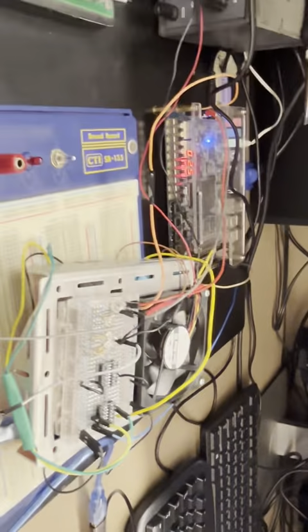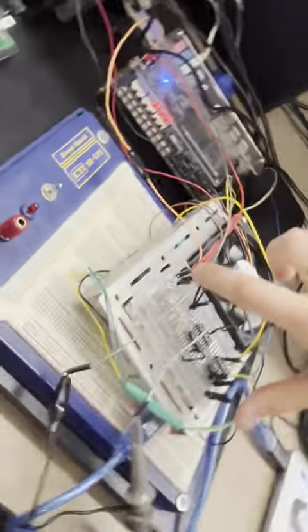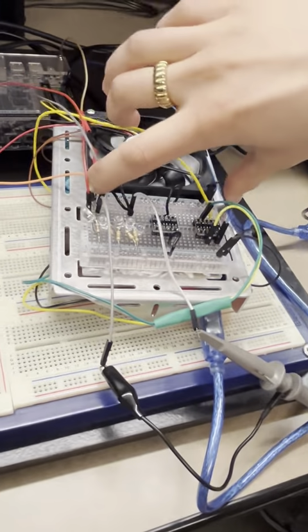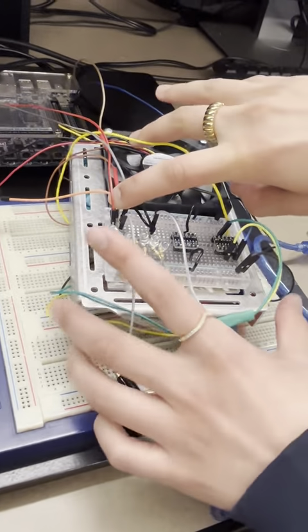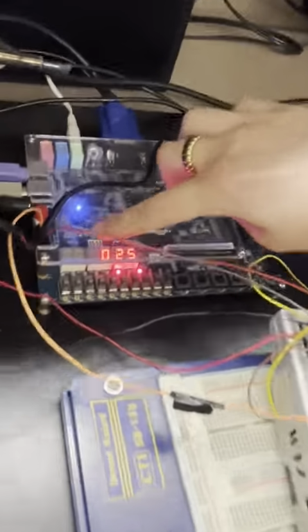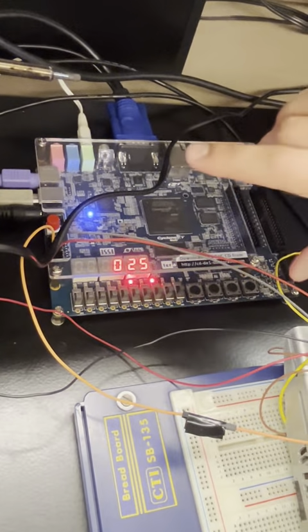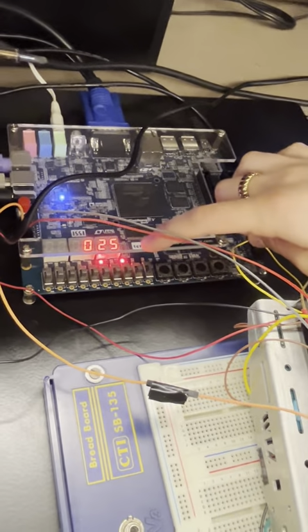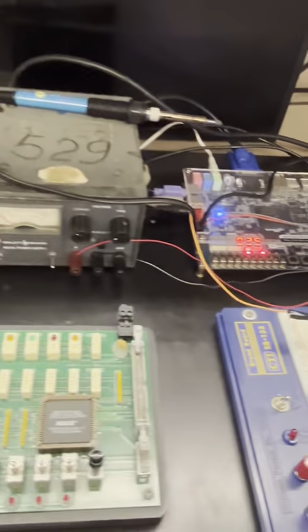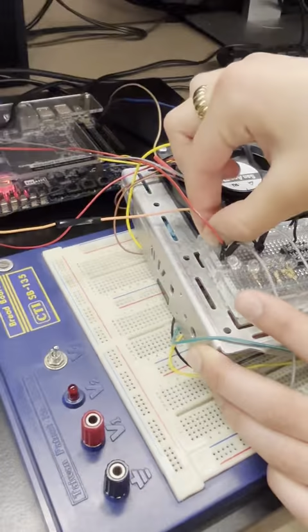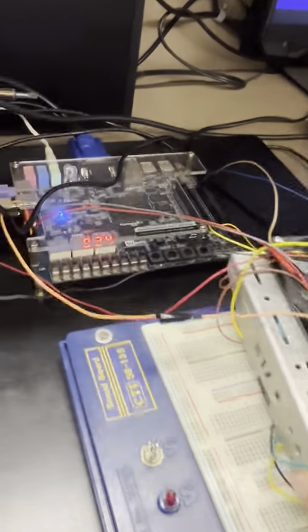So what's happening here is we're emulating CPU temperature using this transistor-based analog temperature sensor, and what that's doing is it's reading, going through an analog to digital converter on the D1 SoC, converting it to a 12-bit value, and then we've calibrated the temperature sensor to room temperature, so it's around 25 degrees right now, and you can see if I heat it up a bit with my hands, it changes.